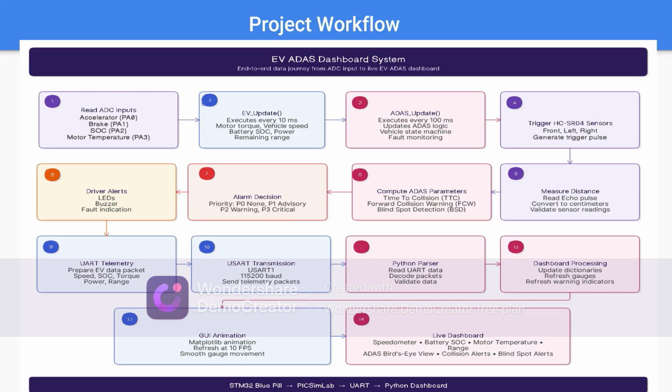This is the workflow of this project. First we read ADC inputs like acceleration, brake, SOC, and motor temperature, and it is updated to the EV updates. These execute every 10 milliseconds and include motor torque, vehicle speed, battery SOC, power remaining, and range.